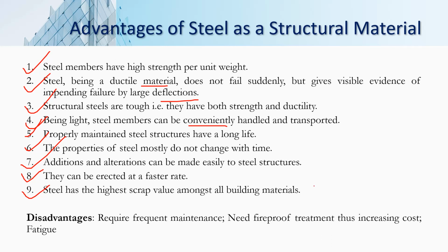Also, there are some disadvantages. Steel elements require frequent maintenance. They need fireproof treatment, thus increasing cost. You know that those steel members, since they are excellent heat conductors, may even transmit enough heat from a burning section. That means steel elements are very vulnerable to fire.